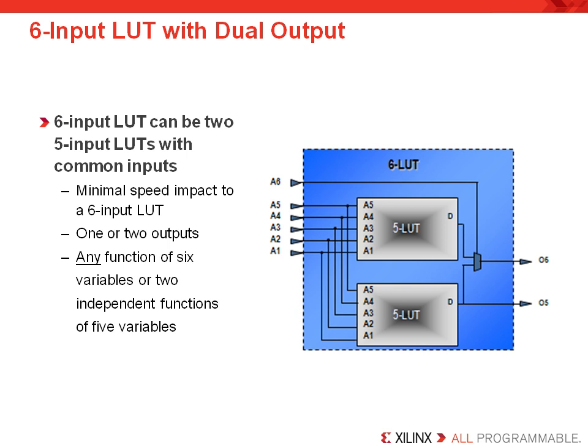Now, combinatorial logic is stored in lookup tables or LUTs. Lookup tables are also sometimes called function generators. The capacity of a LUT is limited by the number of inputs, not by the complexity, so the delay through the LUT is constant regardless of what logic function is being performed inside. Each Spartan-6 slice contains a 6-input LUT that can also be broken into two 5-input LUTs. This allows the resource to be broken down if necessary to help assure maximum device utilization.